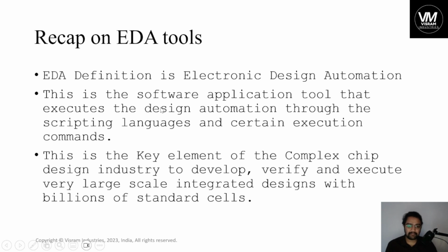It's a simple recap, guys, today. And as I have told, the complex chip design industry uses EDA tools for making their process easy, and we majorly focus on developing the functionality and testing the functionality. So design and verify are the major key steps in the development of chip design. So billions of standard cells. Standard cells can be any sort of elements like logic cells, for example, AND gate, OR gate, XOR, any type of logic cells, or flip flops can be used to refer to a standard cell.